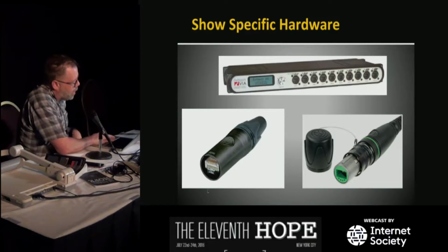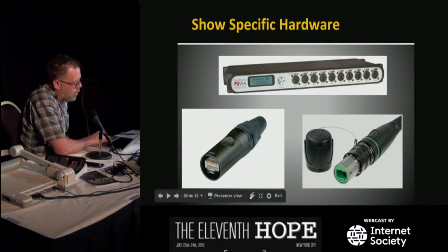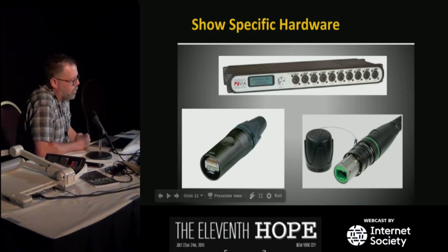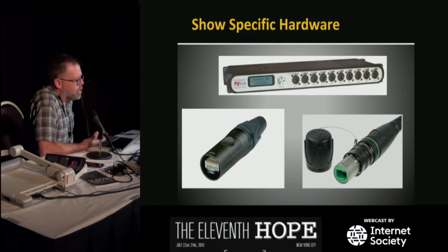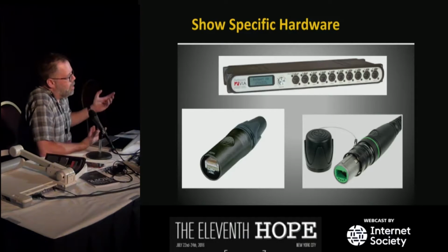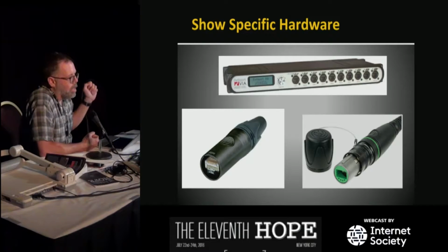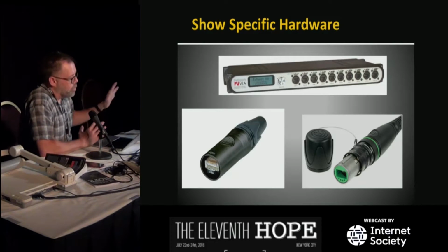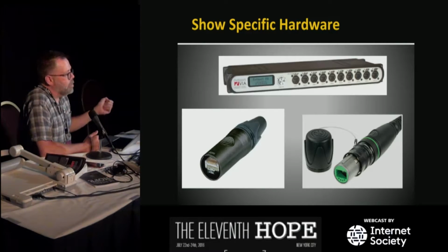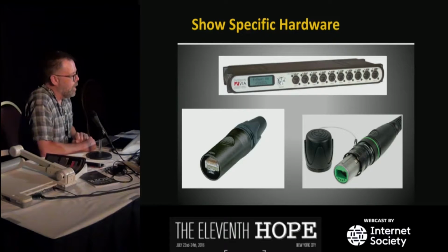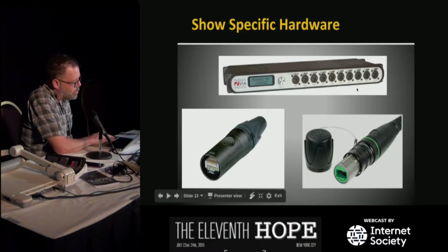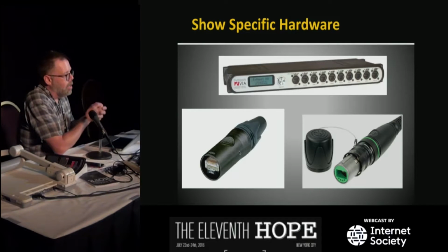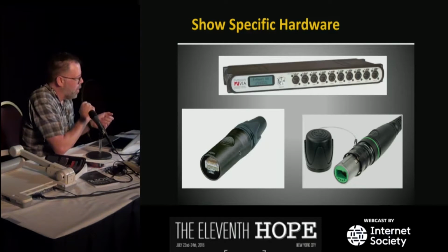Now that same company, Neutrik, is making a similar thing for fiber. That's a dual fiber connector, a heavy-duty thing that's easier for us to unplug and plug. Because in a big machine room in a data center, they're not going to be unplugging their fiber run every day necessarily. In most cases, they're going to plug it in and not touch it until something breaks. Us, if we're on tour, we might plug this thing in and out every single day, throw it in a truck, get in the rain, do something else. So this switch either takes a standard RJ45 or one of these connectors, which is locking. There's no stupid plastic tab to break off.